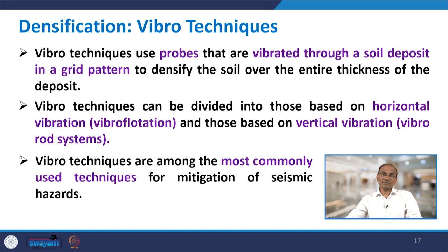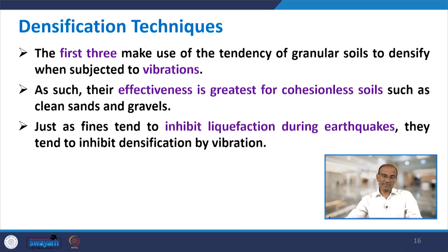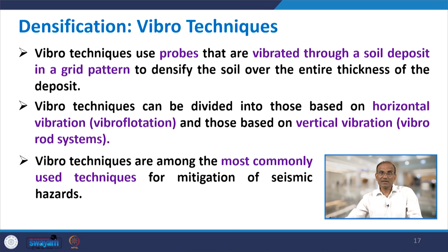So, the first technique in densification is Vibro techniques. In Vibro techniques, probes are used. Probes are a kind of hammer or some device which is struck from a height, that are vibrated through a soil deposit in a grid pattern to densify the soil over the entire thickness of the deposit. Vibro techniques can be divided into those based on horizontal vibration, which is normally called vibro flotation, and those based on vertical vibration, which is called vibro rod systems.